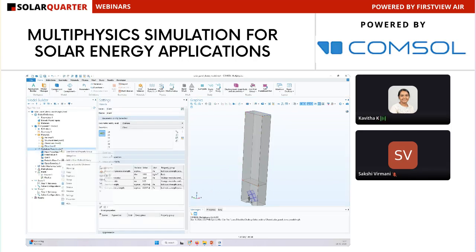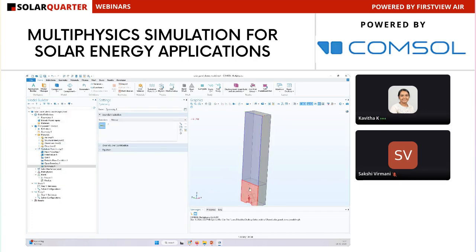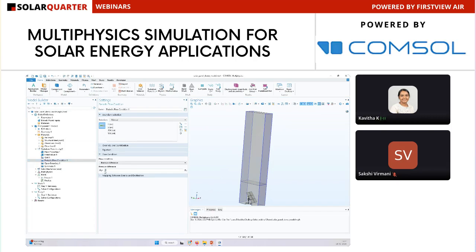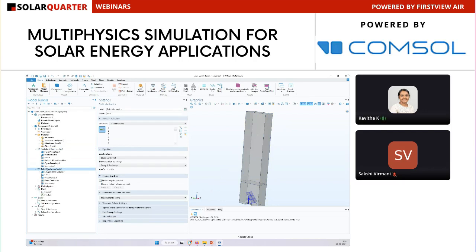So you can right click and choose symmetry boundary condition for the lateral directions. So almost this physics interface is set up, and you can also include the pressure difference using the ordinary differential equation or ODE and DAE interfaces. Then you can set up the same way the solid mechanics physics interface.